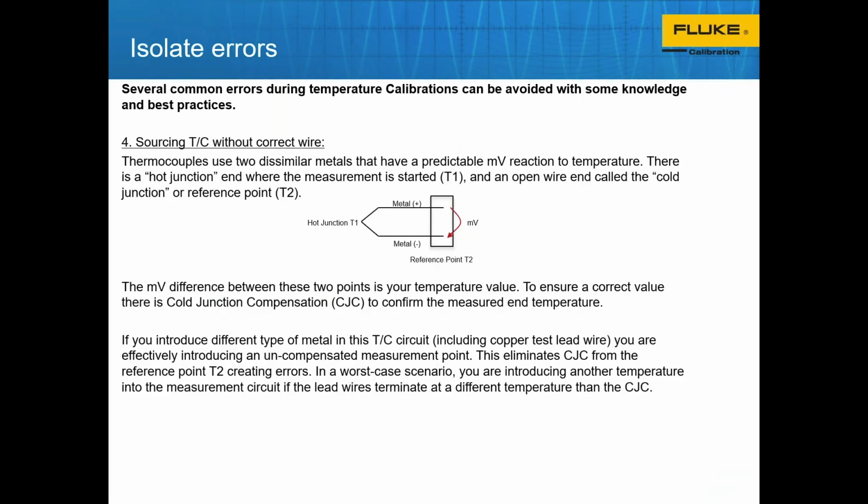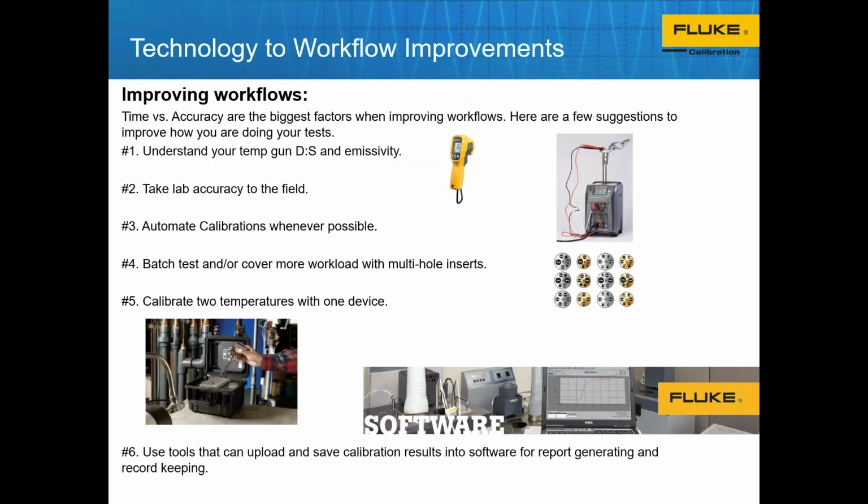Okay, if you're using thermocouples, again, get back to it. Make sure you use the correct thermocouple wire to make your connection points. When you don't, you create errors. Okay, let's talk quickly about technology in itself.